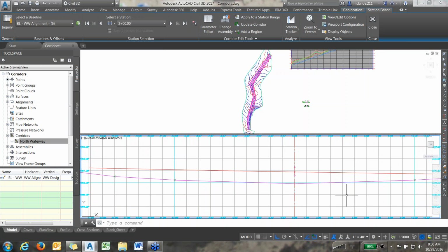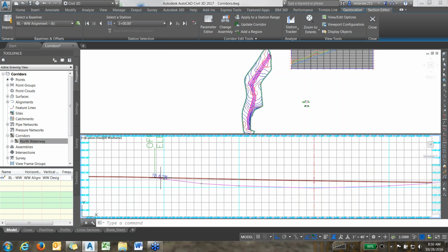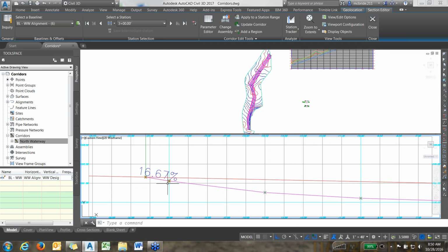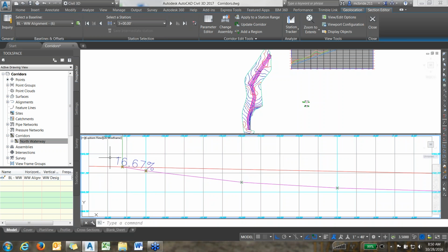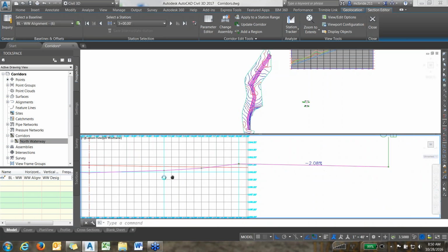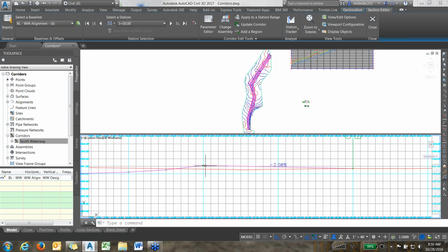And if I go on the left side, the edge of my waterway ends right here at this red point, and then it's cutting another 6-to-1 slope to find existing ground. So it's maybe a 2 or 3 or 4 foot cut to find existing ground, which is pretty good. Okay, so let's just check the right side. And you can see on the right side, I'm still going above the existing ground to fill. And maybe that's not a huge deal. Maybe this can find ground that slopes upward to where it can tie in.